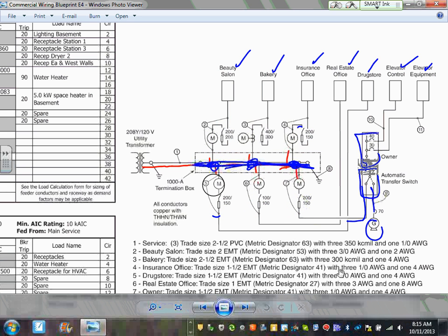They need to charge you, so each one of those occupants has its own meter, either a direct meter or through CTs if it's bigger than 200 amp. All the 200 amp are directly metered. The 300 amp here is metered through CTs. They call them CTs.